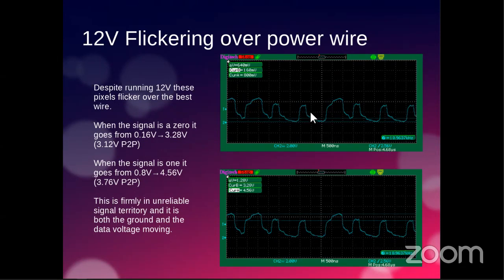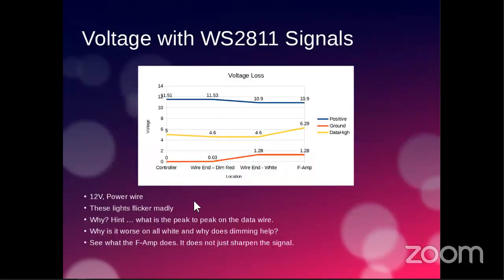And so you get these signals which get into really unreliable territory. And so you'll get 2 types of problems here. You'll either get things where the lights lock on white, or the lights flicker between, say, white and black, or more commonly, you'll start to get random colors. And that's typically because the signal here is being read where some ones are being seen, but the zeros are generally not being seen. And so you get these signals which are quite screwed up, and your lights will flicker all sorts of random colors. And I've seen both with my pixels.